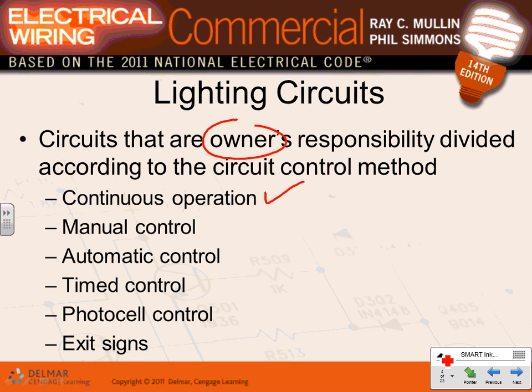They used to do the hallways this way. They feed them from a circuit breaker, no switch, so they are on at all times. This is going away because we're becoming environmentally friendly and want to save energy. So continuous duty means you just throw a circuit at them. Remember when we did a Revit, what did we do for lights? We circuit tagged and switched. With continuous duty you don't switch, you don't tag, you just circuit them. So it's not commonly used.